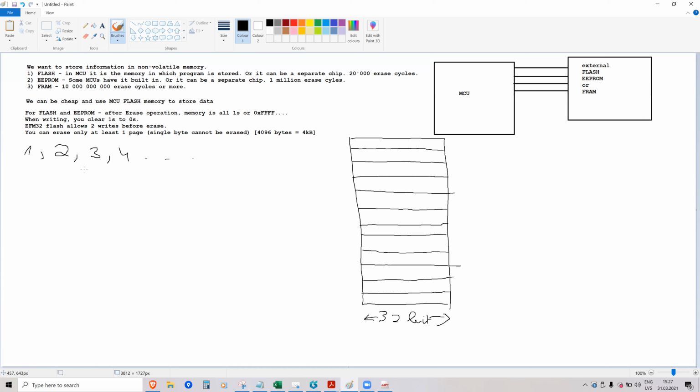And to manage this, we would just write, instead of writing 1 and then erasing the entire page and then writing 2 and then erasing the entire page and writing 3, because then after 20 kilometers it will be worn out, we will instead write the numbers as, I write 1, then after the next meter, in the next memory location, I write 2. In the next, I write 3. In the next, I write 4, 5.